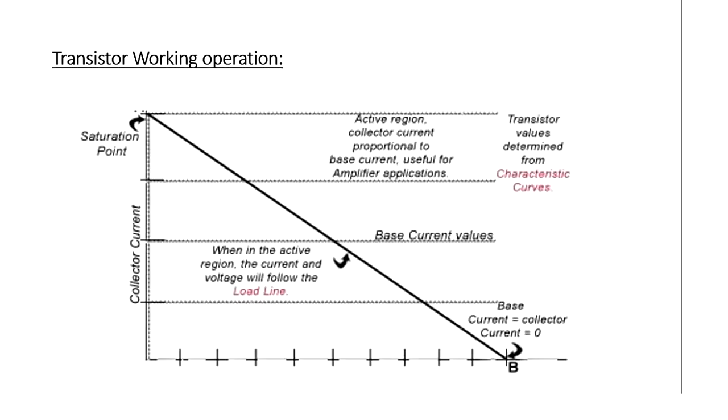In this slide I want to show you the circuit diagram for the transistor's working operation. There are three main regions in which the transistor operates: saturation region, cutoff region, and active region. The active region, as you have studied in previous classes, is the normal operation of the transistor. In this case, the emitter-base junction is forward biased, while the collector-base junction is always kept reverse biased.